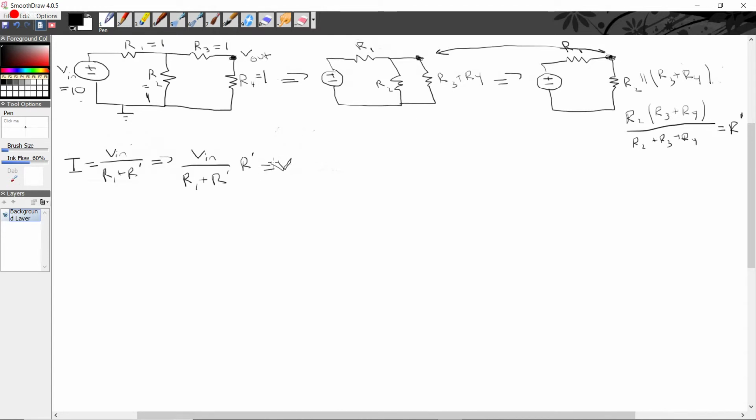Okay, we're almost done. Ooh, a little bit hard to draw there. That's V prime. So now we know what this voltage is. The final thing we have to do is figure out across these two resistors how V prime is related to V out. And that's simple, right? Because they're just in series. So all we have to do again is a little bit of multiplication. What we're going to do is V prime all over R3 plus R4, times R4, is equal to V out.